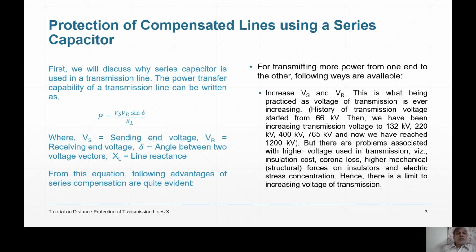Power transferred is Vs Vr sin delta. Delta is the load angle of the generator. And you might be knowing, you learnt in machines, that normal angle delta, when the machine is running normally, when it is taking normal full load, is 30 degree. Because you have to give a leeway when the fault occurs, because when the fault occurs, delta is going to increase.